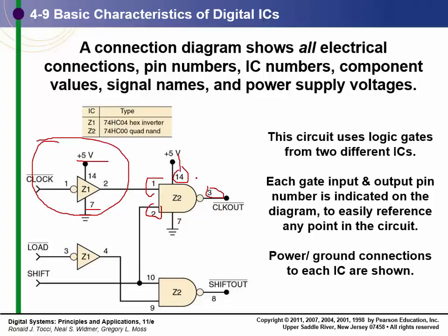In this class, we put these circuits down with gates, and we're going to continue to do that, or do the same thing with flip-flops, and we forget this VCC and ground thing. I don't know how many times I've taught a basic digital course where I draw these circuits, and I go into the lab and they hook them up. Nothing works because everyone forgets VCC and ground. But they do need to be hooked up to every IC, and that is a mistake. This is how we do it in the software. This tells the software, when it goes to lay out the PC board, to hook up VCC and ground to that IC.